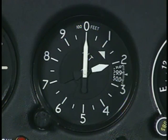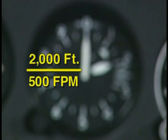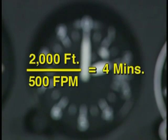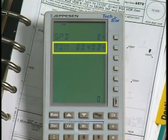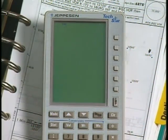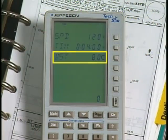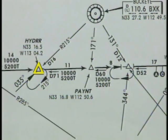Since your present altitude is 12,000, you'll need to lose 2,000 feet. Assuming a 500 foot per minute rate of descent, it will take 4 minutes to reach 10,000 feet. A 4-minute descent at a ground speed of 120 knots will cover 8 nautical miles. The distance from Hyder intersection to Paint intersection is 11 nautical miles. Therefore, if you begin your descent after you pass Hyder, you should be at 10,000 feet, approximately 3 miles before Paint.